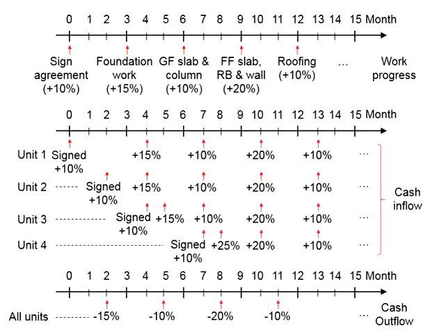In this case, your cash outflow will be calculated based on all the units. The cash outflow will be the leading. That means before completion of the foundation works, you will assume that 15% of the cost has already been paid. Same goes to the subsequent stages.